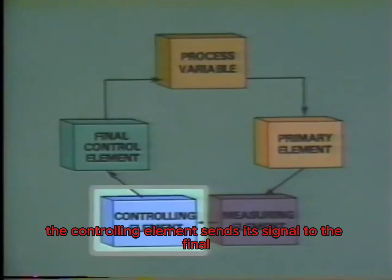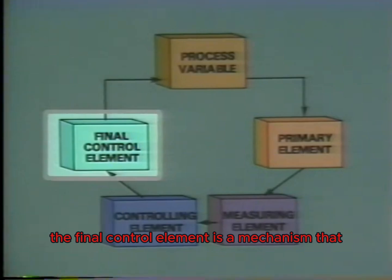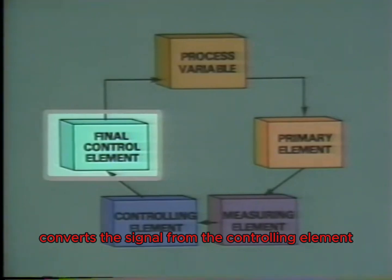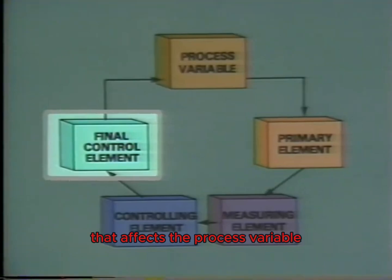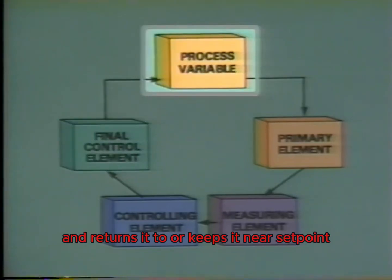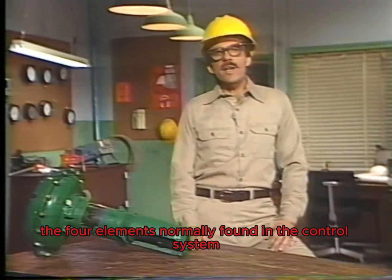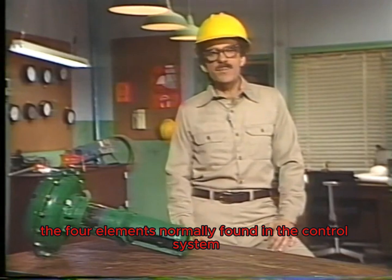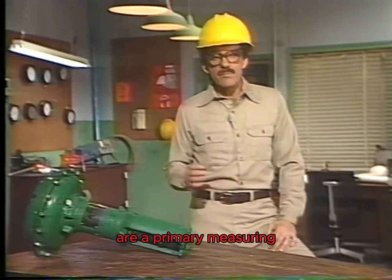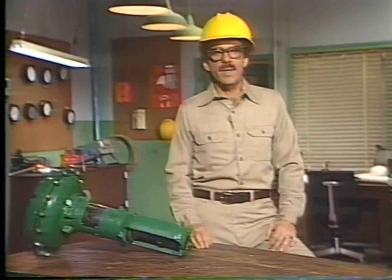The controlling element sends its signal to the final control element. The final control element is a mechanism that converts the signal from the controlling element to a corrective action that affects the process variable and returns it to or keeps it near set point. So, the four elements normally found in a control system are a primary, measuring, controlling, and final control element.